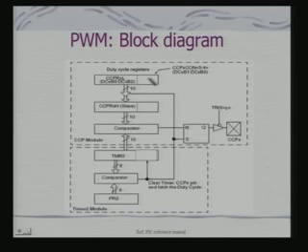What we are talking about here is the duty cycle register. So, I can control the duty cycle through this part of the circuitry, and I can control the period also through this part of the circuitry. And using this, I provide the output on one of these IO pins, and effectively I have to set my TRIS bits appropriately so that I get the output on that pin.